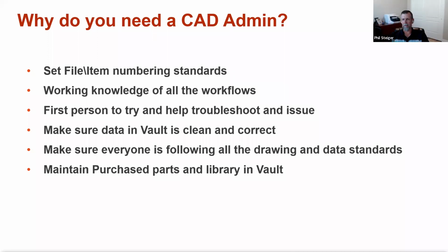Well, then it also comes to whether you're planning to do something else with Vault. Are you going to attach it to your ERP or to a PLM? Then we need to clean the data before we do that. Yeah, and then you have to set a project to clean it. The urgency escalates at that point. Because if you link the systems and want to clean it later, it'll be even harder, because now you're renaming in Vault and renaming in PLM or ERP.